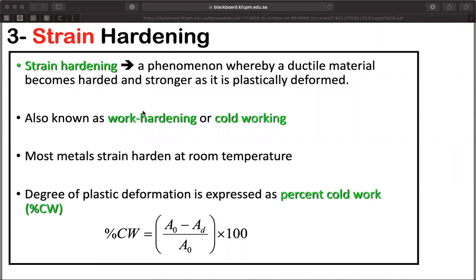The third type is called strain hardening. Now here is strain hardening. What we will do, we plastically deform the material, and during the plastic deformation, we are increasing the density of dislocations. We are activating more slip systems so the dislocations can move. And if we compare two scenarios, let's take scenario number 1, scenario number 2, and let's imagine you're applying a certain shear stress.